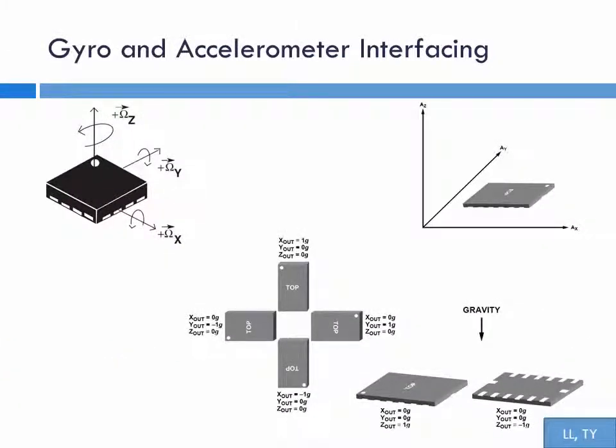On the left, we have the motion sensor L3G4200D using the MEMS gyroscope. It measures the rotational speed, which is the angular velocity of each axis. Looking in the direction of the positive axis, a clockwise rotation will give you a positive reading, whereas an anti-clockwise rotation will give you a negative reading. Note that the angular velocities are transient readings. If the gyroscope stops moving, it will simply show 0.